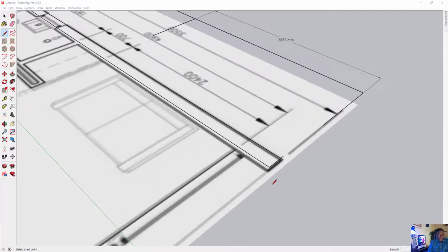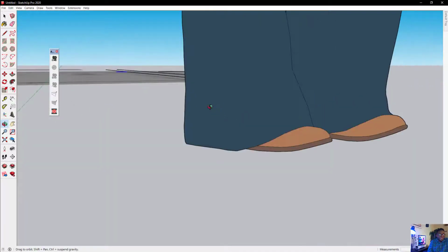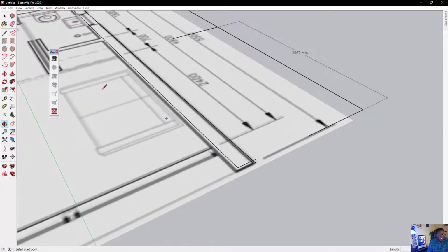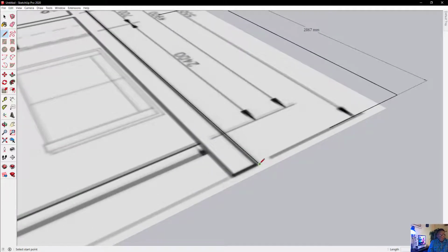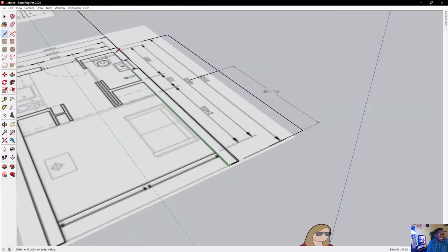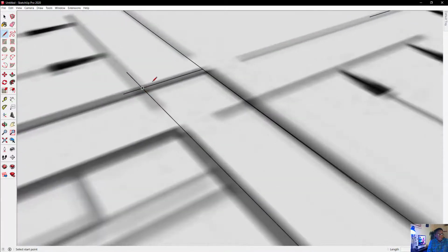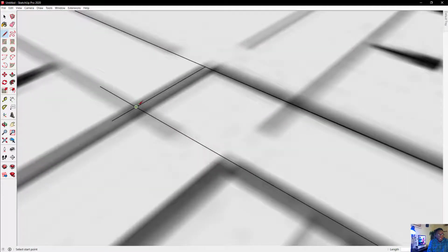And you know, when something is wrong, it's much easier to delete it and actually draw it over. So I'm going to start here and I'm going to go across here and type 200. Now I know that you might be saying, no way am I deleting a line and drawing it over, but in SketchUp it actually works out to be much easier to do that. Now notice I'm getting an intersection here, right? And if I use my eraser tool, it will actually erase these extended lines. So I can actually erase this one here as well, and it will only leave me with those sections there.